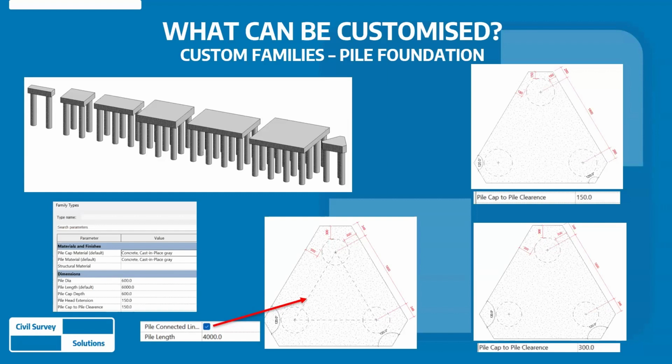Extra functionality was given where the piles are connected by lines. You can turn on and off the line if you want. Now, the reason I put it, sometimes it's convenient to put the aligned dimension. If you just turn on those lines, you can just stick your dimension on those points and the dimension will work fantastic. Now, without this line, it may be a bit difficult depending on how you design your pile or customize your pile and lay out on this three-pile system.